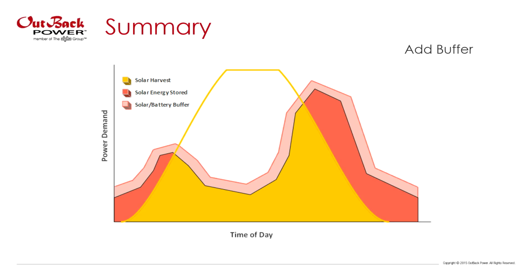All right, so when we add additional energy storage as backup, once you get your solar fully back and functioning, the end user will need to decrease their loads to allow the PV modules to replenish 2 days' worth of energy over a few days. So this is just a note: if your power went out and you oversize your batteries, you have to allow that time for the batteries to become recharged. So you might have to control your loads during that recovery time.